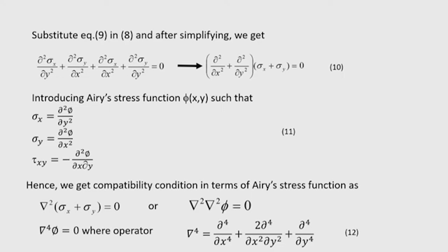We have to find simultaneously the in-plane forces as well as the vertical deflection of the plate. Because of this, bringing the Airy stress function φ into the equation will be convenient.